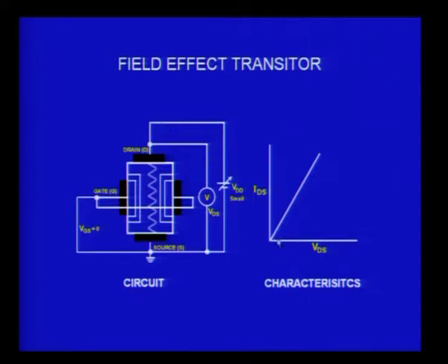So if I monitor that, you will have a beautiful straight line which is nothing but simple Ohm's law, but this straight line will come up to certain value of the voltage. Beyond that, what is going to happen? Now you should remember this resistor, if you measure the voltage at the drain point, it will be the applied voltage. If you measure at this point, it is a 0 at this, because it is the source. In between you have a resistor.